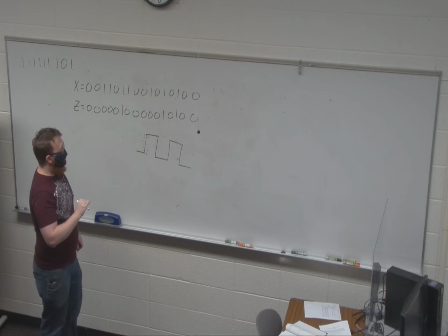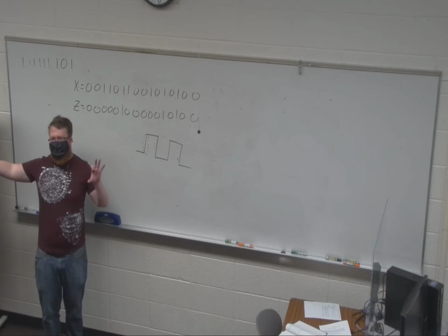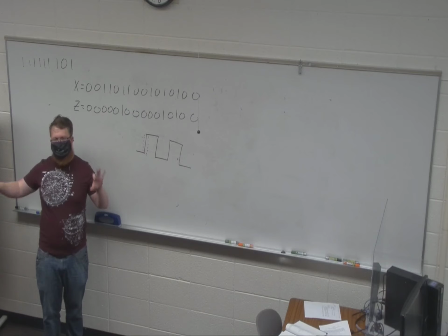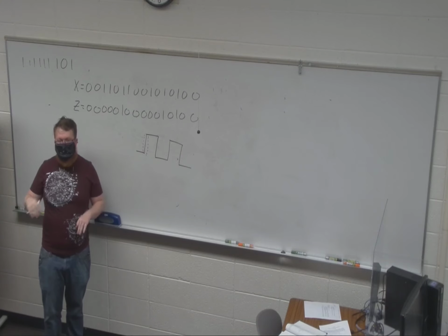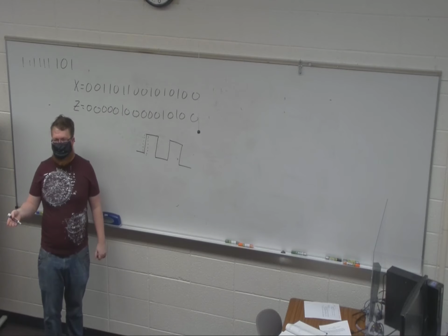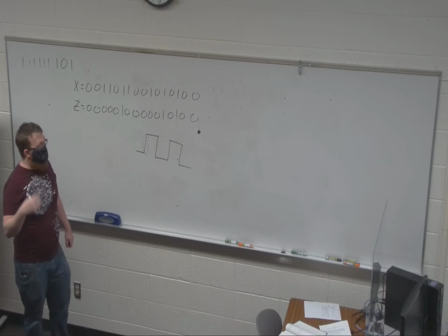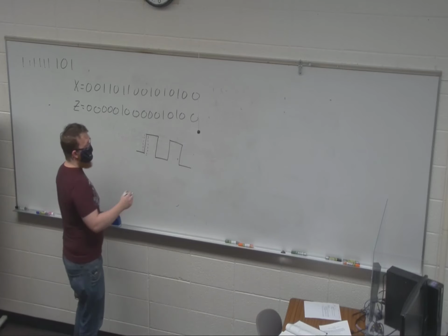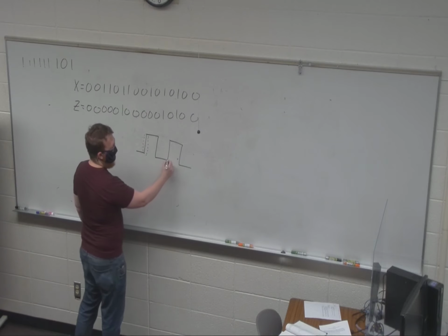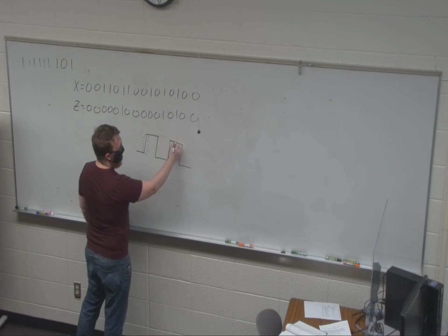The other one is that as you hook up more and more devices to a clock, especially if you don't use buffers correctly, you're going to start getting a lot of capacitance holding that down. And what does capacitance do to a system? It makes it harder to change the voltage. Yeah, it makes it harder to change the voltage. You've got to put more work into it, and it slows it down. So your clock edges then can start looking a little sad.